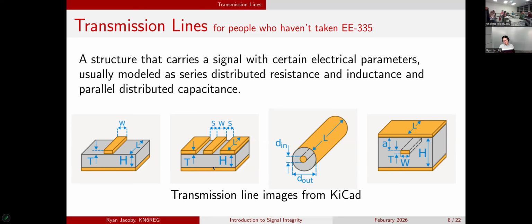I think that helps. But in general, when you pull your ground plane really close in next to your transmission line, you're basically stacking extra parallel capacitance along your trace. That's going to drop your characteristic impedance. So if you need to hit the same impedance, you're now going to need to make your trace thinner and more inductive to account for that extra capacitance.